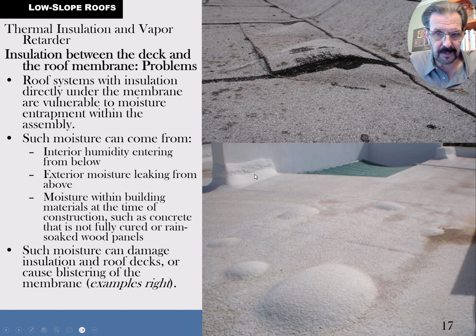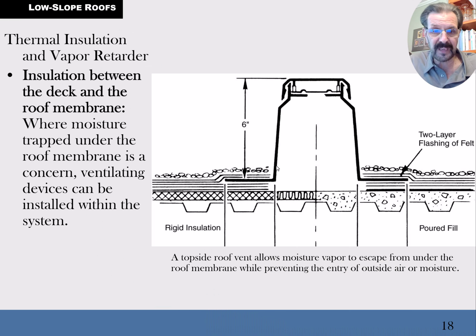down in this spot. It's going to be under tension and maybe loose, but it can be changed depending on the time of year and the temperature. And so the idea to keep it from cracking along this area is they don't glue it down, so there can be some more flexibility to keep it from tearing itself up as there's movement on the roof. And so to get rid of those blisters, they sometimes vent between the roofing membrane and the insulation in order to vent up some of that steam from any moisture that manages to get in there.